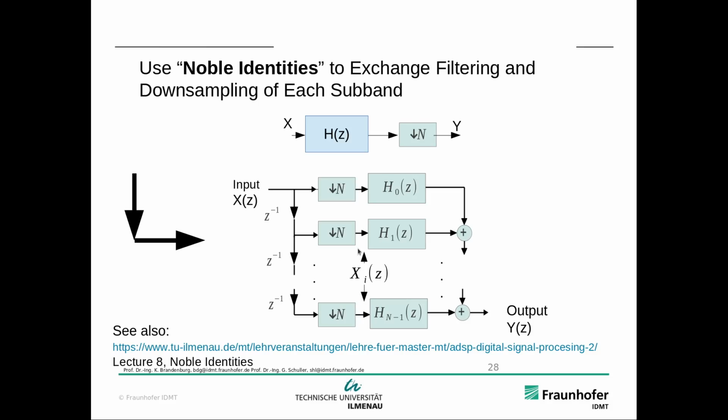So that means here you get N consecutive samples. When you look at the output, here is sample number 0, sample number 1, and here is sample number N-1. Then you wait for the next output of this downsampler and you get the next block of samples, right? So each time those downsamplers let samples through, they let through an entire block.